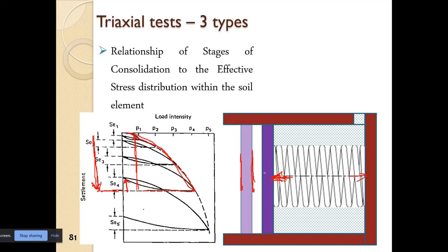All right, so soil, when it is getting consolidated and we release the consolidation load, or the total load which we are applying, some amount of expansion or increase in the volume of the soil happens, but it does not come up to its original position.